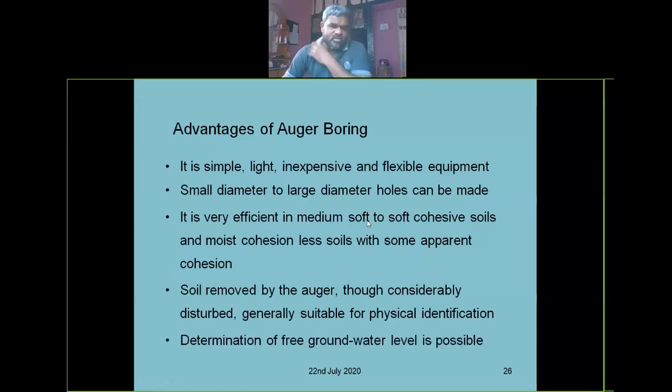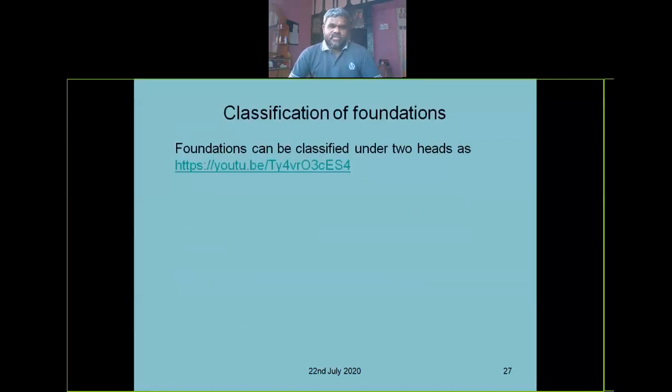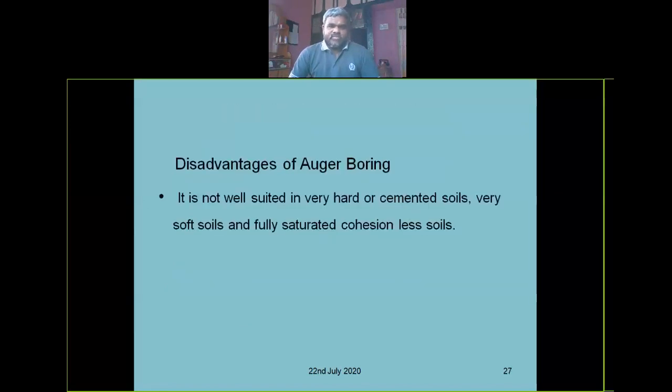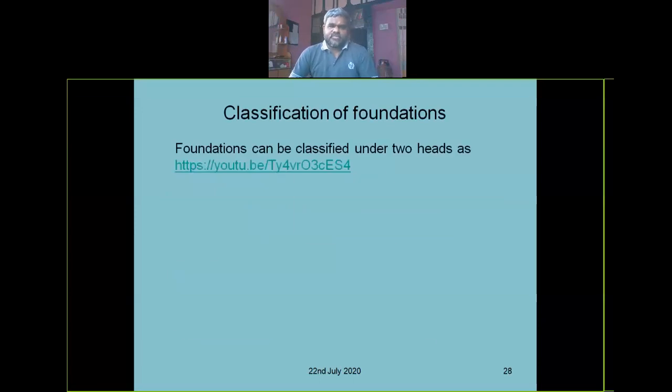Determination of free groundwater table water level is possible. Disadvantages of auger boring: it is not well suited for very hard or cemented soils. Very soft soils and fully saturated cohesionless soils, it cannot be used. This is the disadvantage of auger boring.